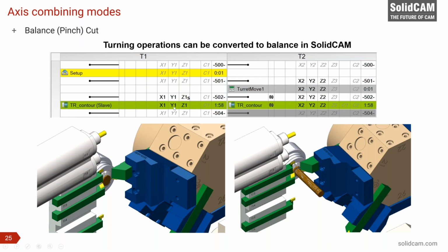It says that this operation will be on both channels. This means that we divide the drive unit. As I said, the drive unit comes from the main spindle. And also we have a description of the axis here, because these tools in this example will also have the same Z-axis. So for example, the turret will not apply the Z2 axis. Both of these attachments will work as for a sliding head machine.